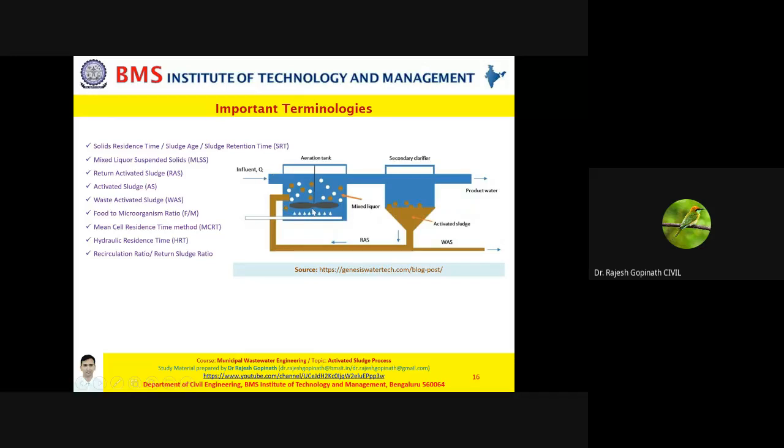Now this is your aeration system, probably a diffused aerator. You see these paddles, so this is a combined aeration, mechanical aeration and diffused aeration both happening. These brown circles are your organic matter. The white circles are your oxygen. Now this is your secondary sedimentation tank, also called the secondary clarifier.